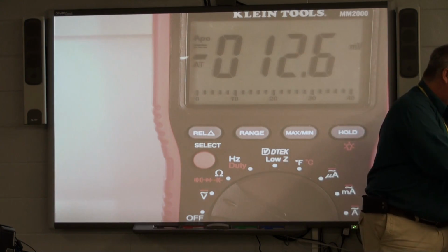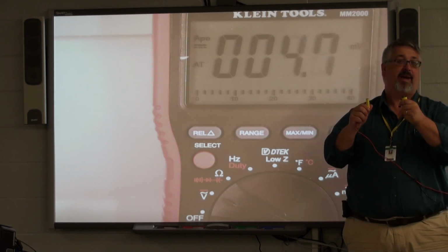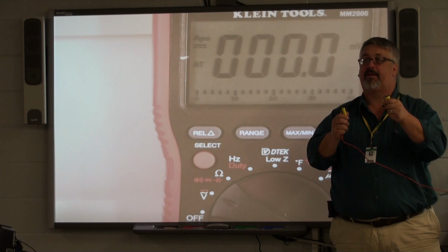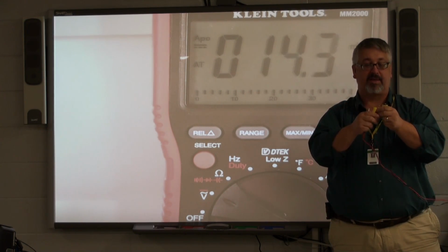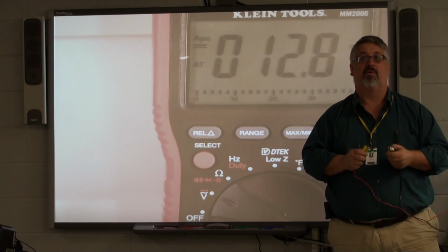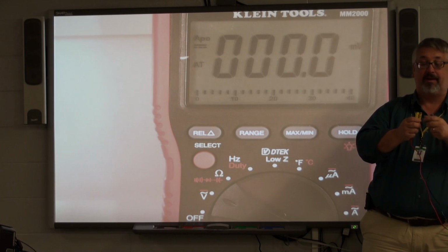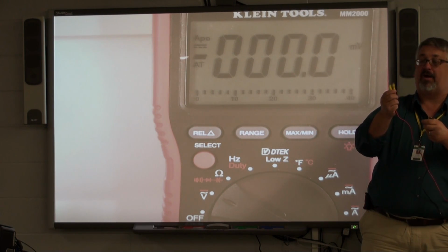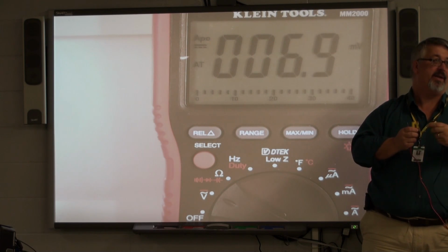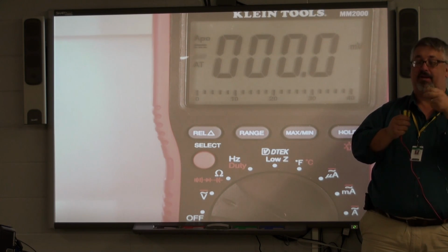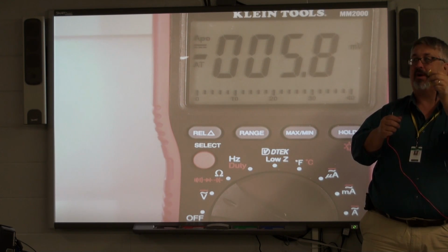But again, the difference in these three, they're all 1.5 volt batteries, but they're going to have different amp hour ratings. This one's going to be smaller. This one's going to be a little more. This one will be a little more. So if I were to take that same LED flashlight and run it off of a couple or three of these versus three of these versus three of these, these are going to last longer. These will last a little less long, and this will be the shortest of all.